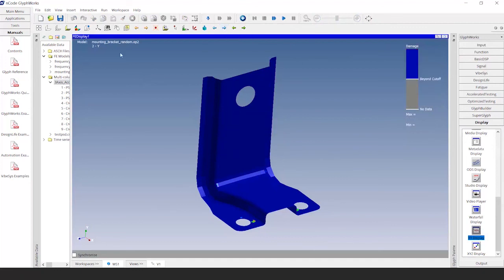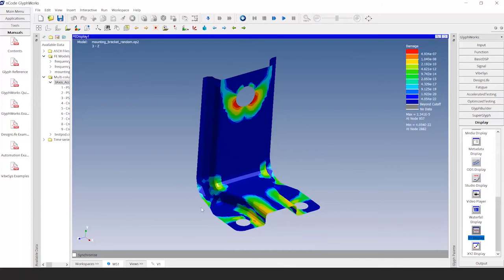So now we're looking at the Y direction. And in fact, the excitations in the Y were so low that we didn't produce any damage here. We've got a threshold that's been established for extremely small cycles, and we just return 0 damage. And then finally, we see the Z direction. And the damage contour we're looking at here is identical to what we saw the very first time when we just did a single axis excitation.